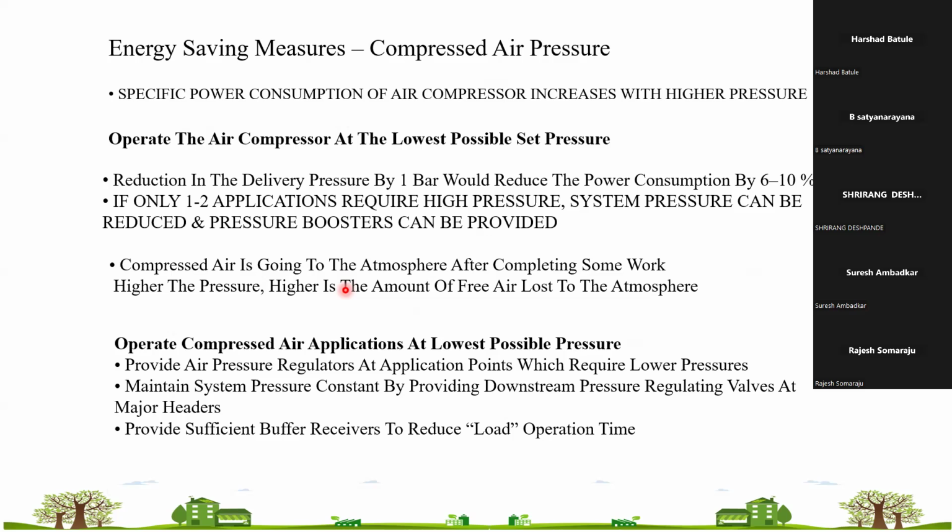Your performance can then be ideal, we can say, at good conditions. So your cool air intake is most important. If you are allowing ambient air to your compressor, it will deliver a good FAD.